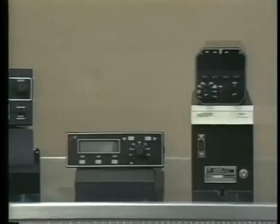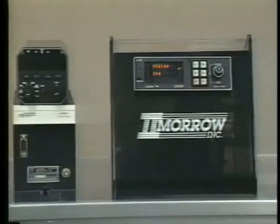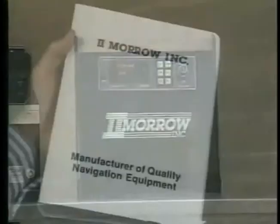The surface type, foliage, and seasonal changes can affect the speed of the radio waves and decrease their accuracy. There are several types of Loran units available, and their capabilities vary considerably. Besides bearing and distance, some receivers provide wind direction and velocity, fuel consumption, and other types of information. You can determine the features and limitations of the particular unit you're using by referring to the owner's manual or to placards located on the instrument panel.